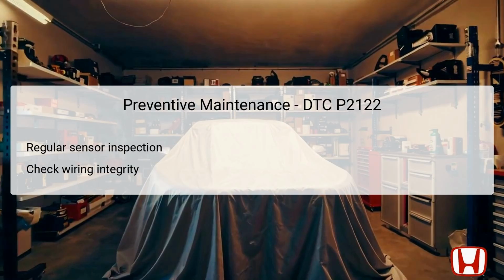To prevent the recurrence of DTC P2122, routine preventive maintenance is crucial. Regular inspections of the APP sensor and the connecting wiring harness can identify potential issues before they escalate into overt faults. This could include checking for fraying wires, corrosion, or loose connections that can interfere with the signal integrity. Additionally, utilizing diagnostic tools to assess sensor performance periodically can ensure that it remains reliable over time. Ensuring that all electrical connections are secure and free from contaminants is vital to maintaining sensor health.